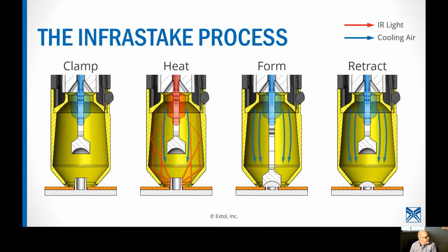Polypropylene is an example. A door, like you saw the video of that tall boss that was being staked, that was polypropylene. And what was it? 4 seconds of heat and 4 seconds of punch. Yeah, and we've got another slide. Scott just further narrowed it in just a little bit. I've got another slide coming up really soon that shows another process, and we list the cycle time right on it. So we'll have a couple examples of that.